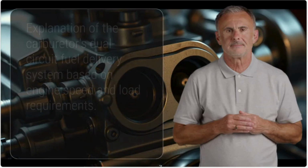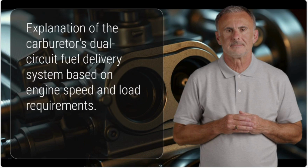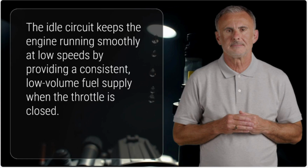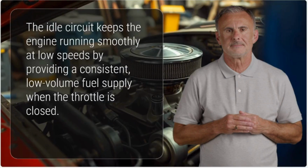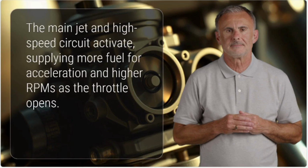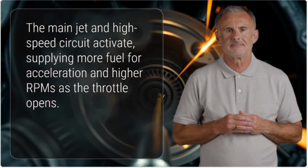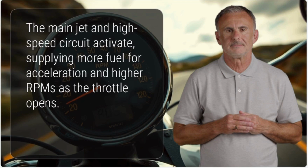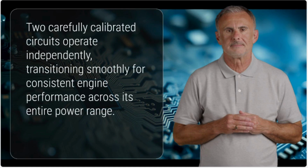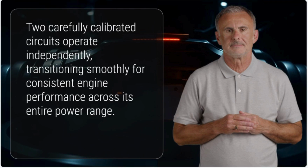Operational circuits in the carburetor. The carburetor uses two main circuits to deliver fuel depending on engine speed and load. Idle circuit: this circuit is active when the engine is running at low speed or idling. It ensures that the engine receives a consistent, low-volume supply of fuel, even when the throttle is nearly closed. Main, high-speed circuit: as the throttle opens and the engine demands more power, the main jet and high-speed circuit take over, delivering a larger quantity of fuel to support acceleration and higher RPMs. These two circuits operate independently but are carefully calibrated to transition smoothly, providing consistent performance throughout the engine's power range.